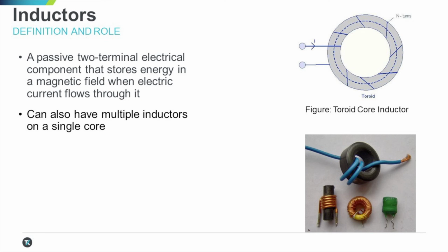It is also worth mentioning for our webinar that an inductor can also have multiple inductors on a single core. Now, it is also worth mentioning that in contrast to theoretical inductors in textbooks, the inductance value of a real inductor is dependent on multiple things, particularly current levels, temperature, and the frequency of operation. In a power supply, these characteristics vary in real time with operating conditions.